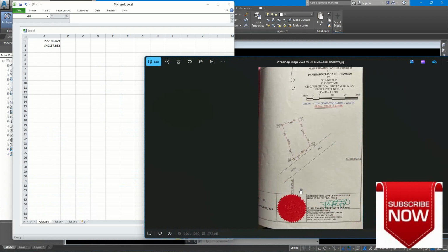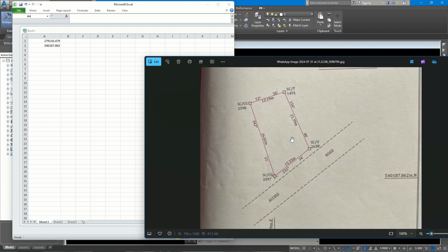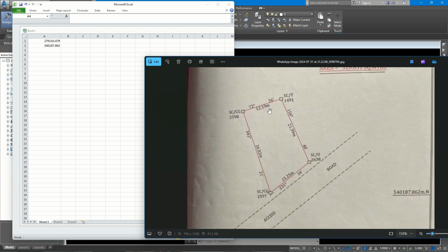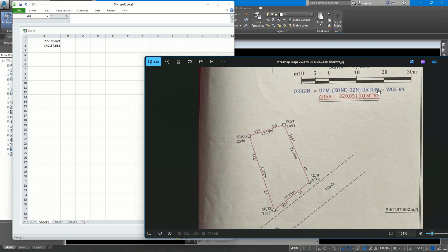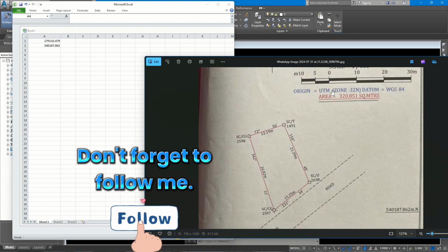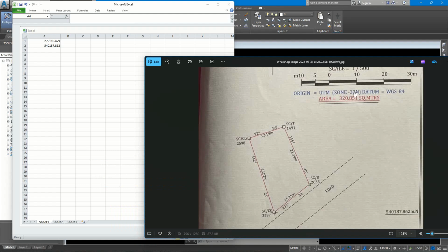Now for this purpose, I have the site approved survey documents drawn by the surveyor, and I want to present same into the AutoCAD Civil 3D workspace. I will take note of the coordinate and as well the coordinate transformation system. This is a UTM, and this is in zone 32, WGS 84.